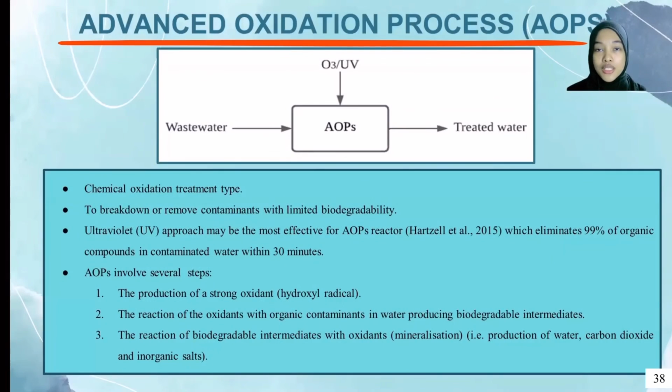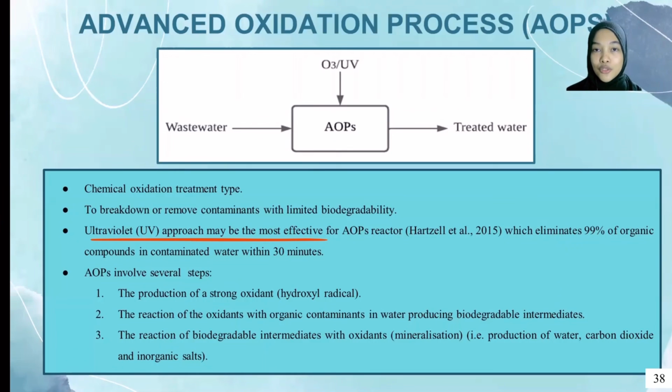So advanced oxidation process, AOPs, is the treatment that we use to treat the wastewater as it can degrade the organic compounds, which are isopropyl alcohol, IPA, and acetone. This treatment can remove contaminants, and the UV used in this process is the most effective in eliminating 99% of organic compounds in contaminated water. This treatment process involves several steps, where in the last step, we will be producing water, carbon dioxide, and inorganic salts.